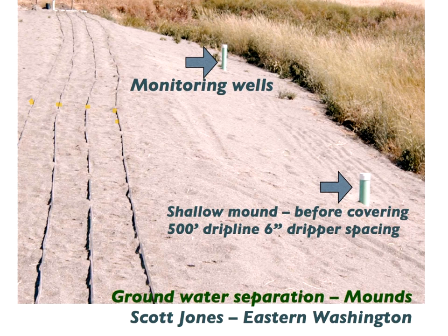It really does work very effectively, and in the end, it is not terribly expensive because you save a lot of sand. You don't have to bring anything like as much sand. And this particular mound was being fed with septic tank effluent. This was not secondary treated effluent. This was septic tank effluent, as I said, with extremely good results. And it's easy enough to check on this with the health department in Washington State. They have a lot of hands-on experience.